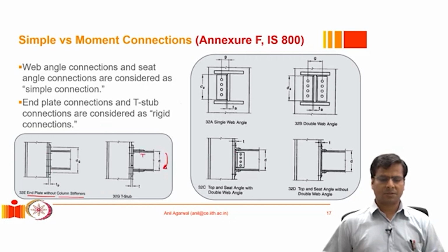This is subjected to tension, and this flange would want to pull away from the column. Then this T can resist this load by slightly deforming in this way. The flange would deform this way, followed by the web remaining straight, and then the top flange of the beam would be tied to this one.